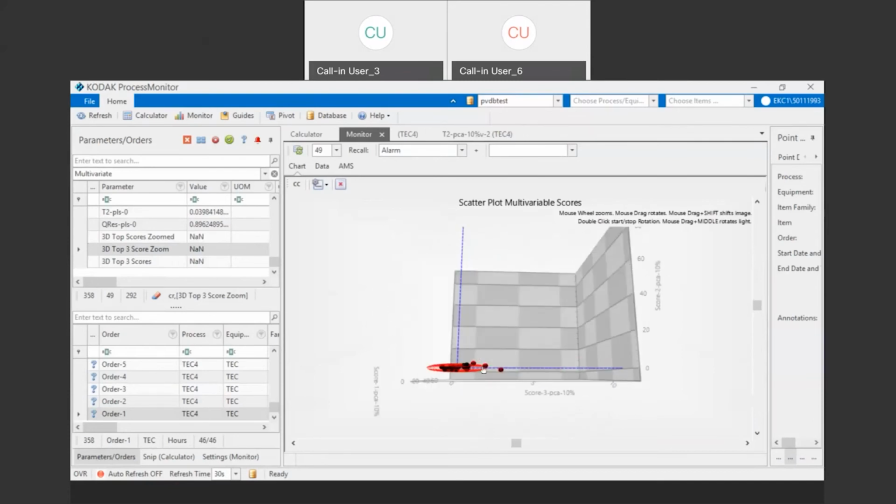This is a three-dimensional portrayal of all those 40 batches. And the control is an ellipse, actually an ellipsoid, which is the equivalent of the 2 sigma line. It's a 95% confidence limit. And if I showed you 3 sigma, it would enclose all of the data sets, all the data points. All these are the individual points, the orders that we talked about beforehand.